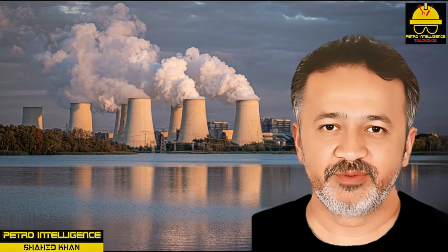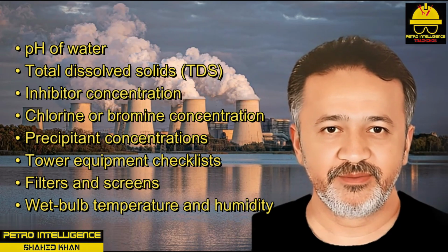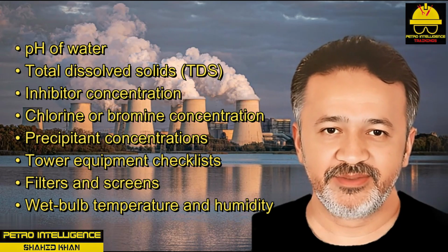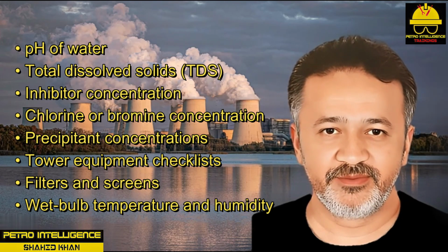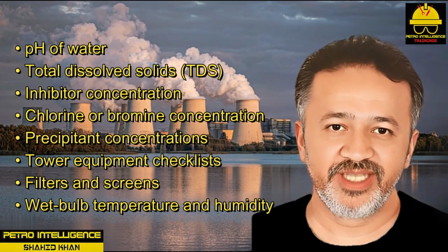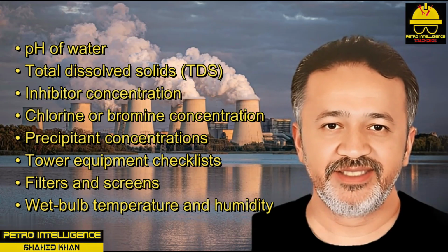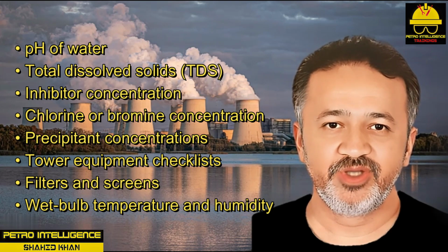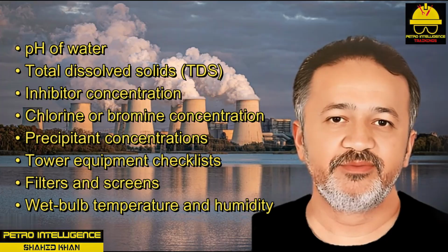Operators are responsible for testing and checking pH of water, total dissolved solids, TDS, inhibitor concentration, chlorine or bromine concentration, precipitant concentrations, tower equipment checklists, filters and screens, wet bulb temperature and humidity.